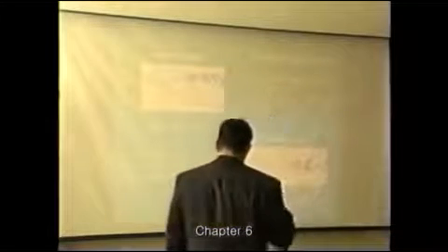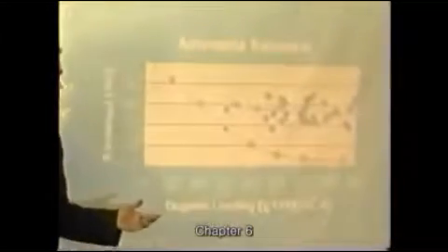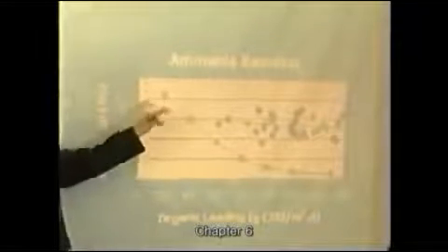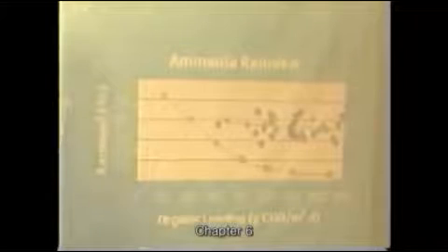Looking at nitrification, nitrification is the same. What happens is, if you want complete nitrification, you would need to load your system at about 200 to 250 grams per cubic meter, if you want to remove sufficient ammonia.